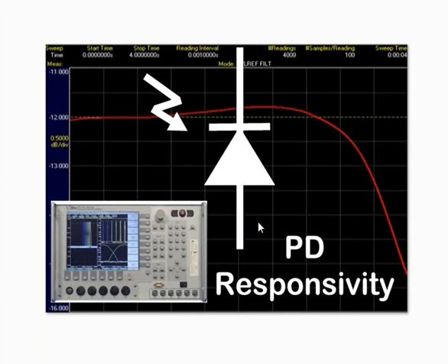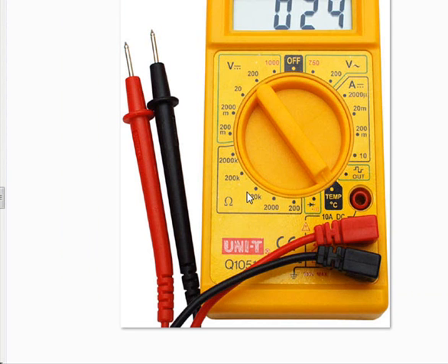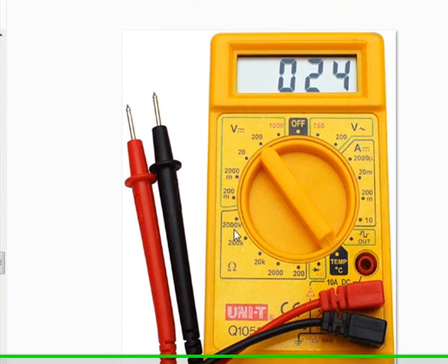The trick is you have to measure it in the resistance mode. We know that we have a resistance mode in the multimeter. Go to the resistance mode, select 2000K. This is 200K, and select 2000K. And then start measuring it.